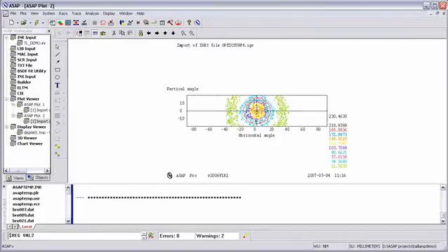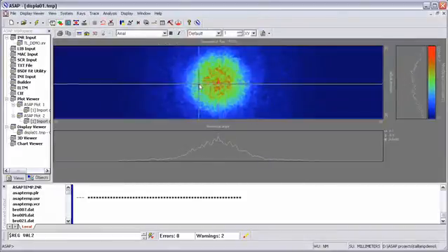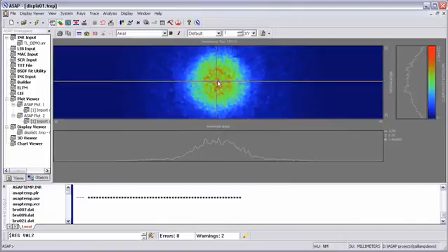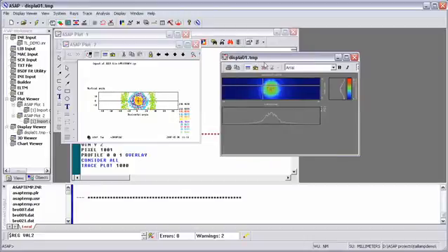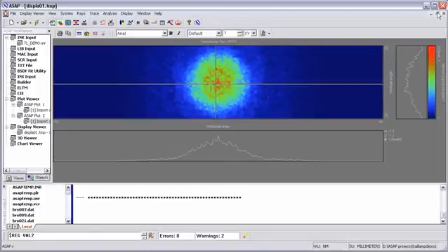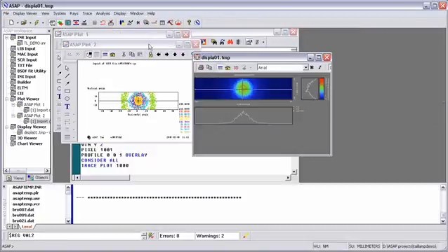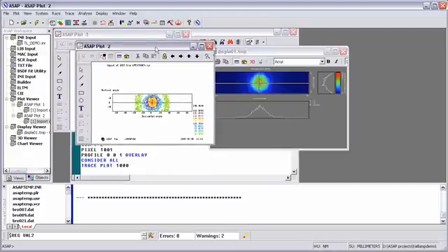What we've also put out, which may be a little more familiar, is an isocontour plot in the angle space of the turn signal, so we can look at the angular contours, as well as a picture plot where we can interrogate individual pixels if we want to look at specific values. And you'll notice that the resolution for this particular demo is a little bit low. We've traced a smaller number of rays than we would normally trace for an entire simulation. If we wanted to do the final output on this, we would run upwards of 3 million rays. In this case, we've run only a couple hundred thousand. The 3 million ray trace might take 45 minutes to an hour to complete.